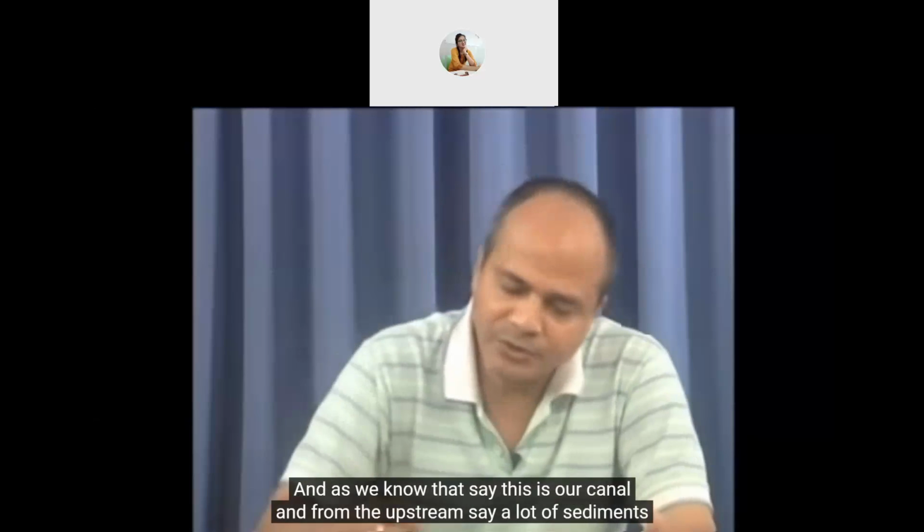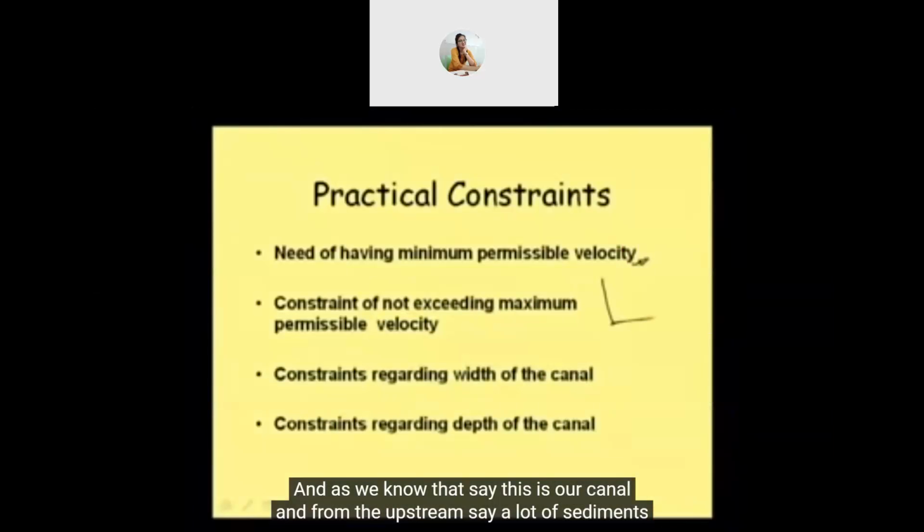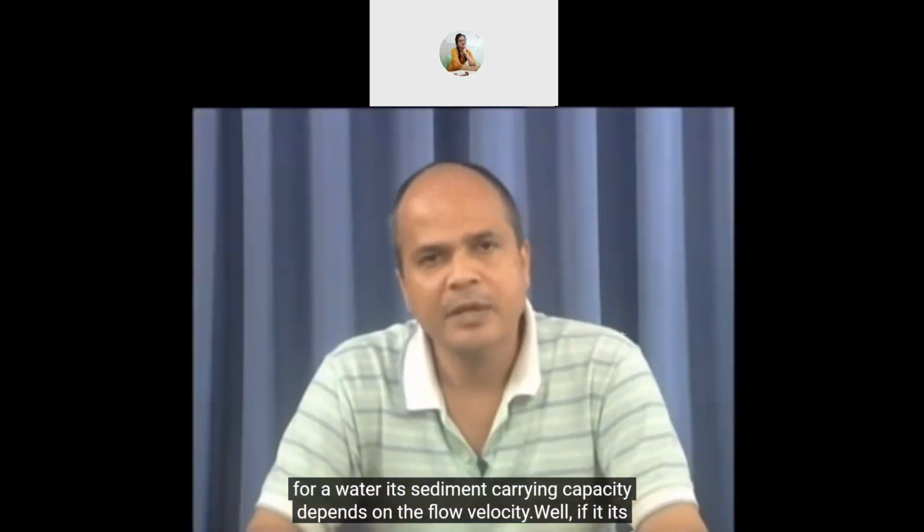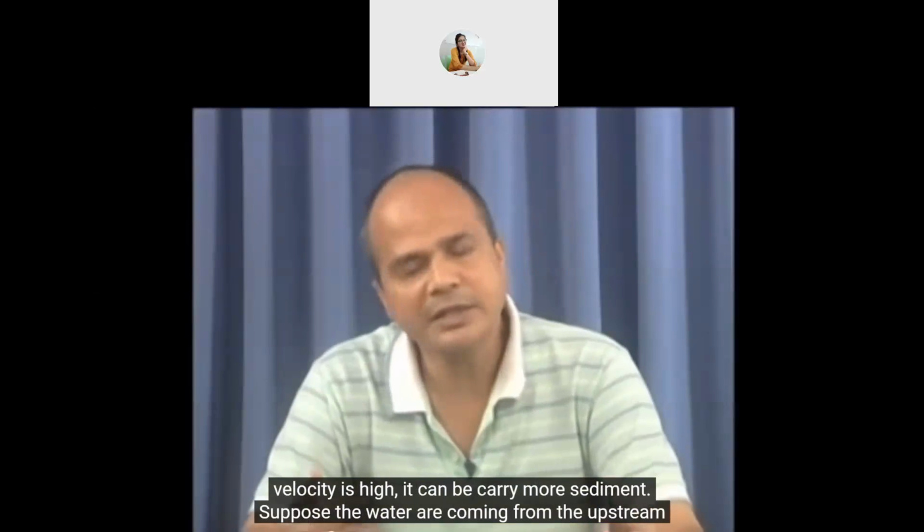And as we know, say this is our canal, and from the upstream a lot of sediments are coming, and then sediments are settling down because the flow velocity is less. For water, its sediment carrying capacity depends on the flow velocity. If its velocity is high, it can carry more sediment.